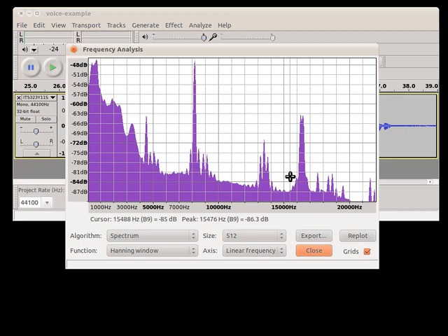We see a peak here, which is quite high, of around 8,000 hertz. Maybe that's just some noise that was measured, maybe some feedback or some interruption from my laptop when I recorded that. So the voice frequencies are mainly in this range. The rest are just other frequencies from the air conditioner, from people speaking, from noise in the communication system, which, although they look high in this plot, if you plot them linear, are very, very, very weak. So it looks something like this.